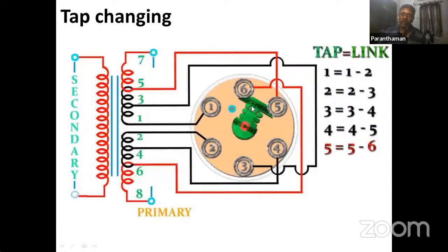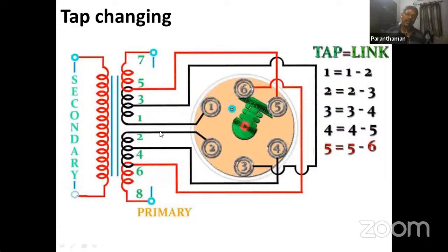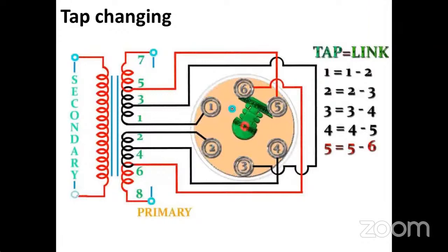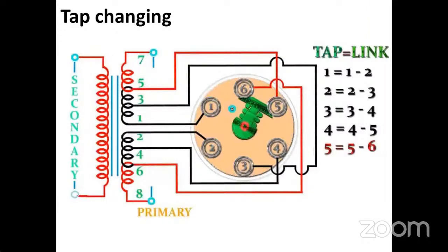While rotating this to 3 and 4, what will happen, sir? In the intermediate position, make and break. Yes, 1 and 2 will break. But the on-load tap changer adopts the principle, first make, then break. During that time, it will be connected with a short-term resistor.